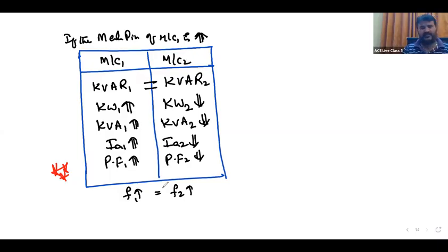The point is, to shift the active power from machine 2 to machine 1, increase the mechanical power input. Listen, lastly, we will go for a break, just 2 minutes, wait for some time. Here, active power sharing depends on the prime mover input. Reactive power sharing depends on the excitation. Therefore, reactive power is controlled with excitation, and active power is controlled with prime mover input. And active power sharing also depends on the prime mover characteristics.